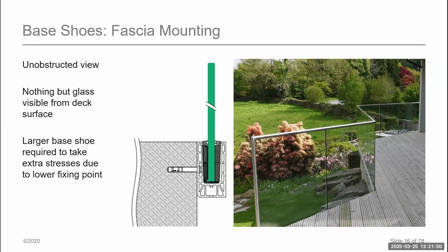So then when you're doing the heavy lifting, you are not required to have some type of crane or whatever to lift that glass into place if you are dealing with some type of high-rise application. Another advantage that we'll see with fascia mount is it will allow the element to become part of the facade lower down. And when the occupant is looking from the space that they occupy, they actually don't see any of the guardrail elements in their view, and it provides the cleanest, most celebrated panoramic view possible for this type of application.